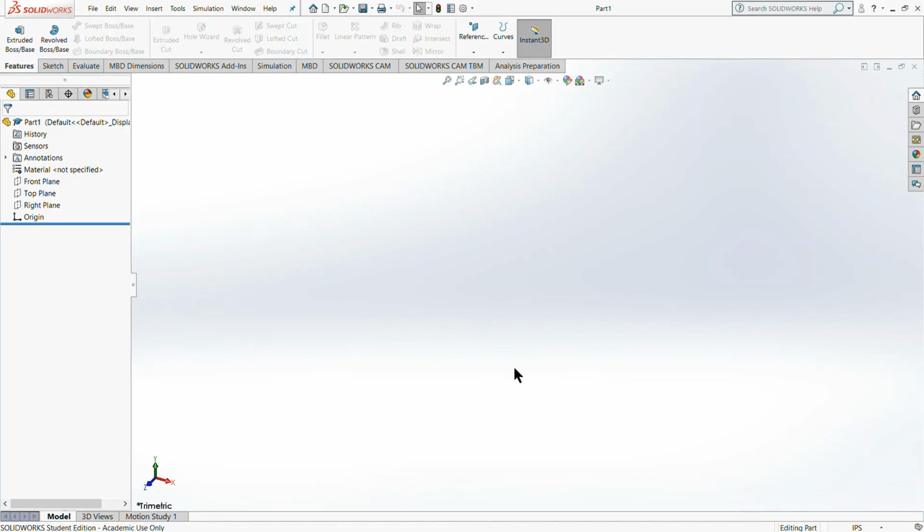All right. Now for the good part. So what I've done is I've started up SolidWorks, and it gives you three options to start off with. You can either make a part, an assembly, or a drawing. I'll explain the difference between the three of these. So a part is essentially one cog in the larger system. It's one singular model. It's whatever you want to design or sketch or draw, and it's one singular component. That's the key thing to remember.